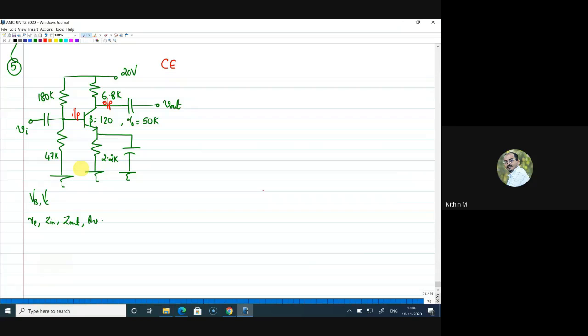Now, at the signal of interest, when I provide an input signal here to the amplifier, I am assuming that all these capacitors will offer a very low reactance, so they will remain as short, right? So since the capacitors are remaining as short, the question is again back to Mohan: can you tell me what kind of amplifier this is?